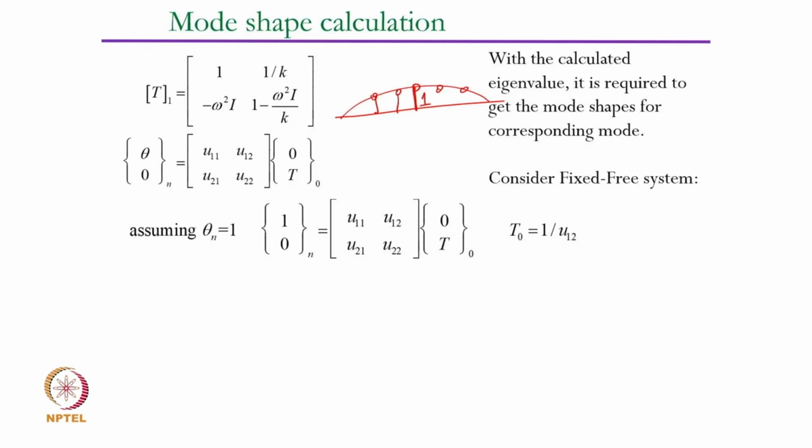So, in this torsional vibratory system, we say that at the end there was a flywheel here and then there were so many elements here. At the end, if this deflects theta equal to 1, then in relation to that 1 unit twist, what are the twists in the rest of the elements? When we assume theta at n equal to 1, we still do not know how much this value is.